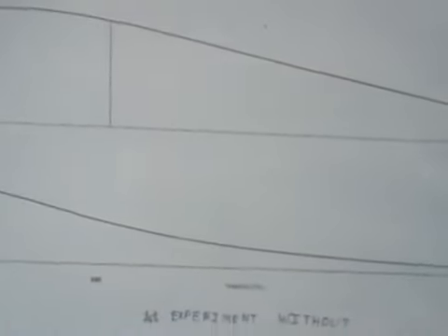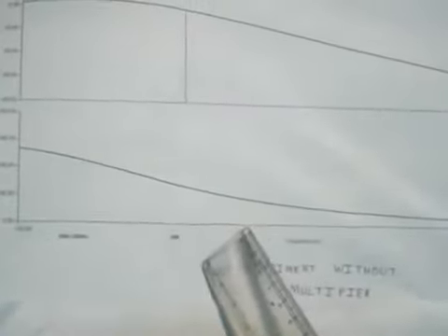Now let us compare the Bode plots from the simulated and the hardware implementation. When we use the kit without the multiplier, we get a big bandwidth, that is, I'm getting a bandwidth of 180 Hz in simulation, and through the hardware implementation I'm getting a bandwidth of 140 Hz. And as we keep on progressing while applying the control voltages, we can observe that the bandwidth decreases and the gain curve becomes a lot finer.